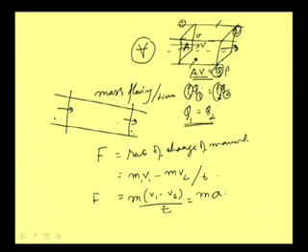Now, by energy conservation, we mean that whatever energy we have here, it is not that it should be identical downstream, but some energy can be lost. So, energy at this point minus the loss of energy during this flow gives the energy at the other point.